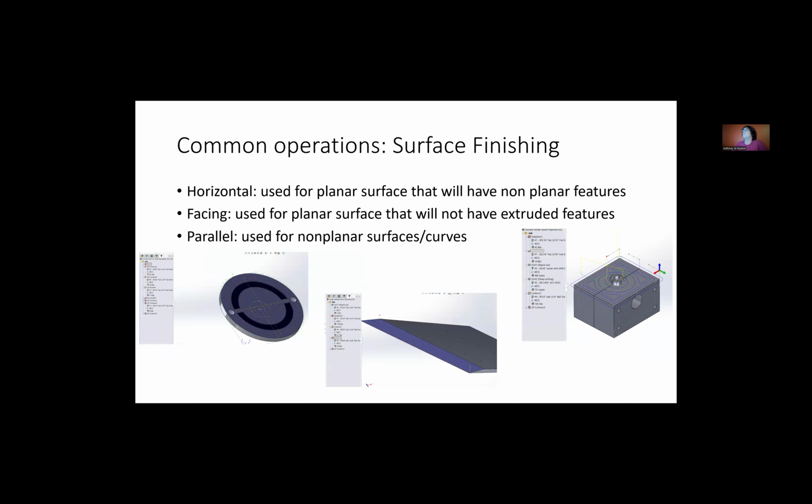So we went over some roughing paths with the pocket and the adaptive clear. Now we can talk a little more, and the contour stuff was a lot of the finishing path stuff as well. But some more finishing path operations you could have are in the realm of facing or surface finishing. So let's talk a little bit about the difference.